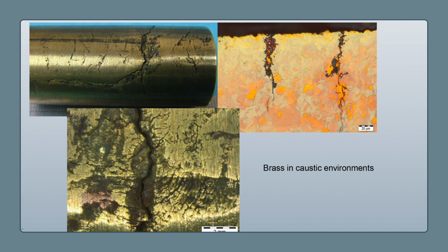And the tube at the top left was actually removed from the bottom of the condenser turbine unit. It was in service for 40 years. The guys acid cleaned the tubes with sulfamic acid, which from literature we've seen is commonly used. However, during the cleaning process, the alloy showed some dezincification and due to the caustic environment started cracking.